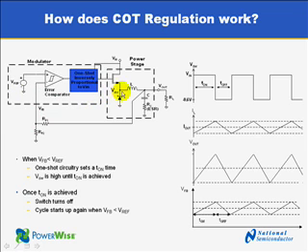Let's have a look at the switching node. Here we see the timing diagram of the switching node. During the on-time, the switching node is connected by the MOSFET to VIN. During the on-time, the inductor current is rising linearly. The voltage at the output capacitor is increased accordingly. The feedback voltage is tracking the output voltage.